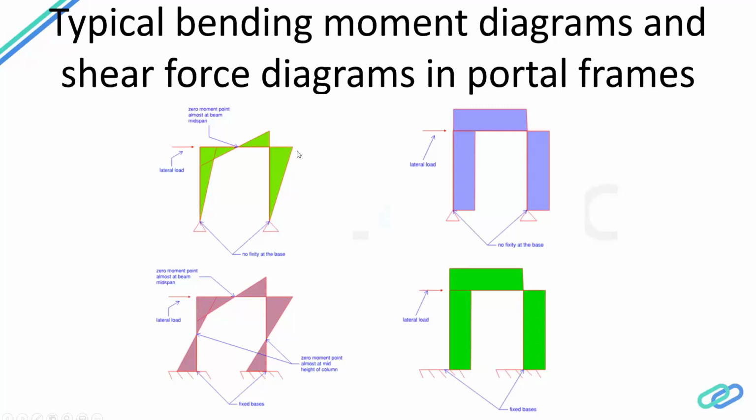And then once you move to this joint, when you apply this lateral force, this is the bending moment that's developed in the beam, which goes from a negative value to a positive value with a constant slope, because there's a constant shear force acting on this beam, which we are seeing on this side. And then once you reach the column, you again see this bending moment at the column joint, and then as you go down to the pin, it reduces to zero, right?